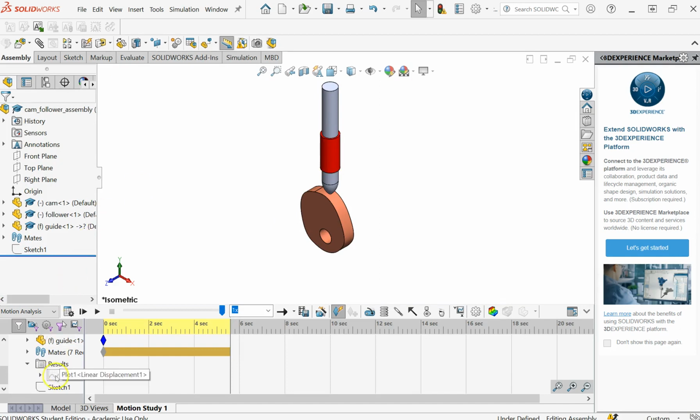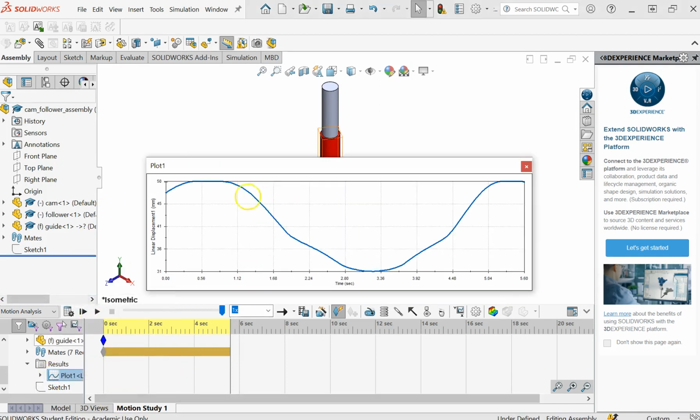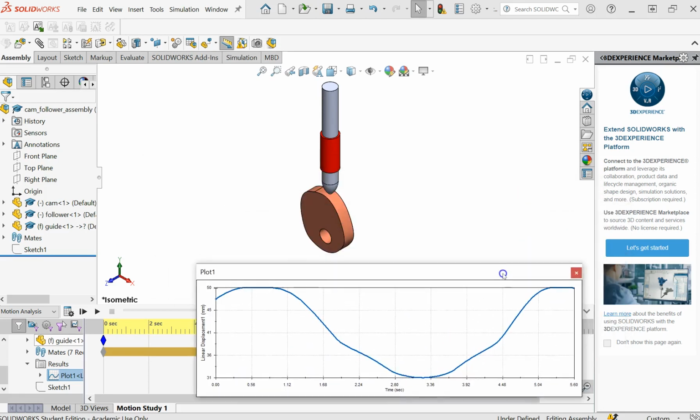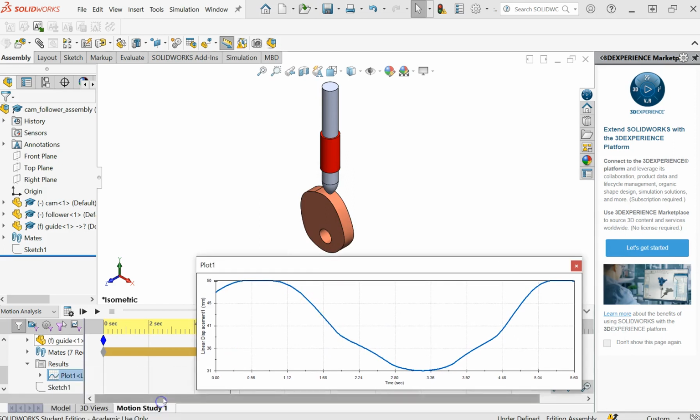And here I generate this plot, which you can see. You see here, it is going up and staying up. It's a little bit dwelling, and then it is going down, down, down, a little bit dwelling here and going up and repeating itself. And you see, it's not super perfect, of course. There are these variations, although it's smooth, but it's not as good as maybe you want, or maybe that's what you want. So these depend exactly on what? On those distances that I had in the cam. So if I choose different distances on the cam, then the amount of dwelling and the shape of this profile would definitely change.